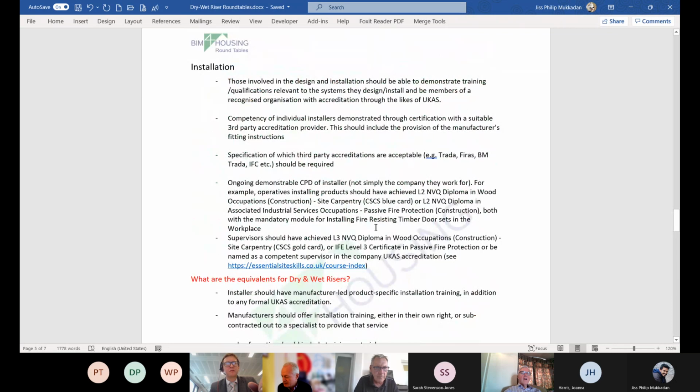I don't. I can remember an installer complaining to me that exactly that is not what happened. That the risers were separately purchased, and complaining that they were not hydraulically correctly designed and so on. I mean, the standard BS 9990 for all of these things is not written by people who know about hydraulics. It's largely written by fire officers. So there's a view that perhaps it needs an update.